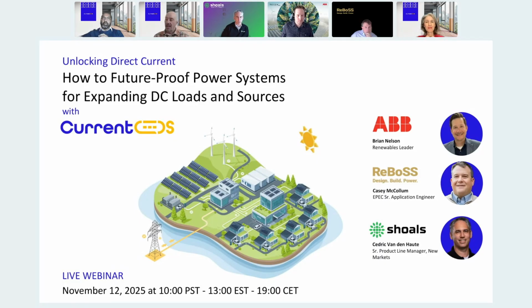Yeah, I would just add that for us, it's not as much finding the components. We can find them with partners like ABB or some others. It's sometimes that the components that exist are not always listed or registered components by UL, so we have to be a little more creative about that. Some of those components are certified for other standards, but very often we have to get on-site certification by a third party because of that problem.